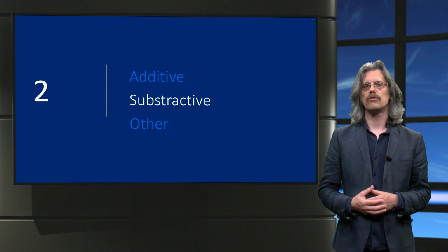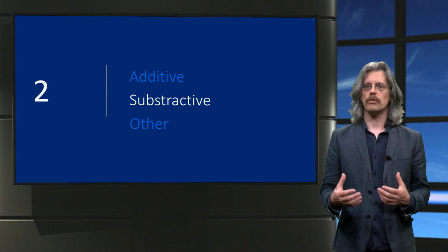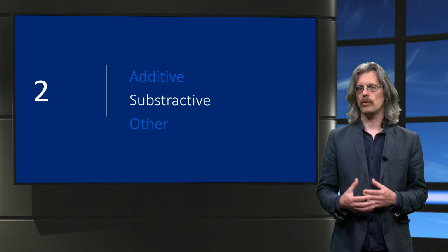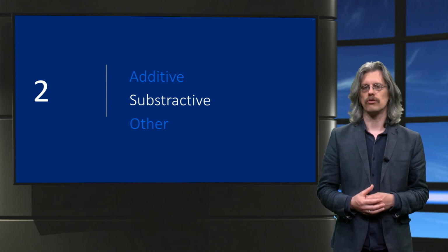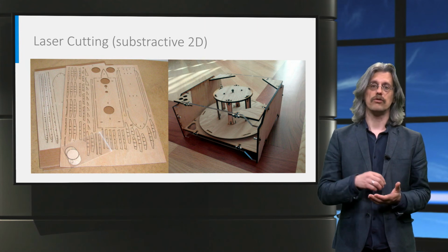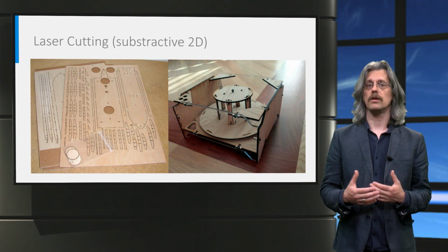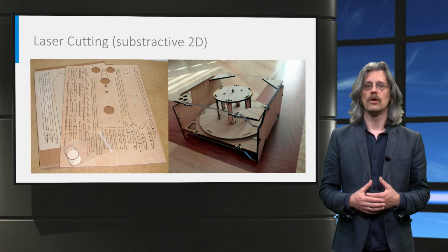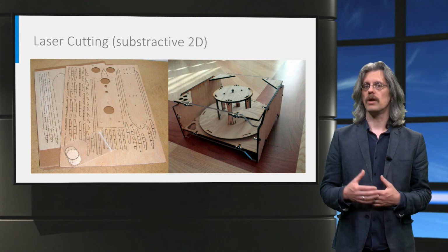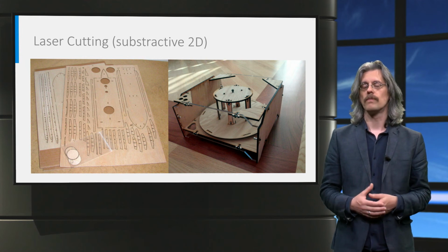The second set of digital fabrication techniques is subtractive. Here we start with stock material that is removed by a digitally controlled system. For today we will look at two well-known and powerful approaches. Laser cutting can cut through and engrave several sheets, for example plastic, wood and leather. This technique is extremely fast compared to additive manufacturing, while modeling can be done in basic vector drawing packages, such as CorelDRAW or even PowerPoint.